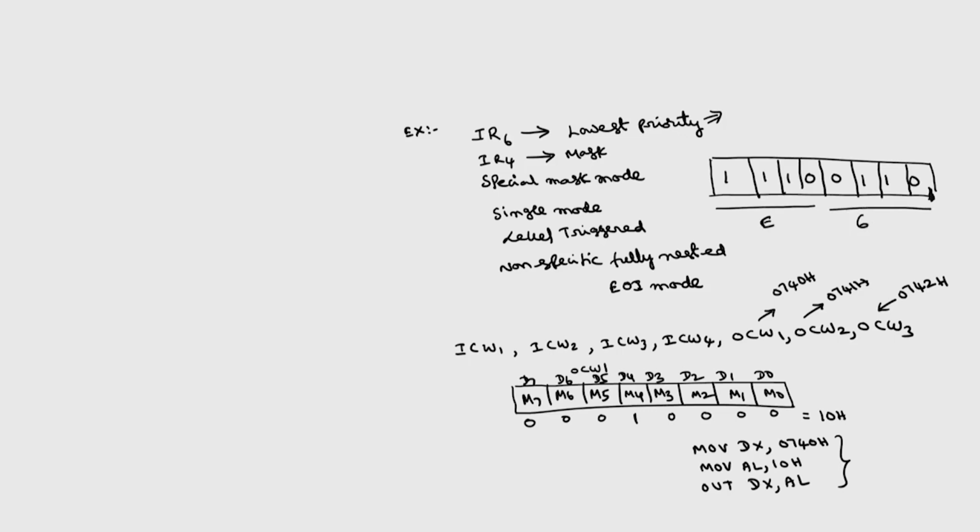The corresponding instructions for this one will be MOV DX, 0741H, MOV AL, E6H, then OUT DX, AL.